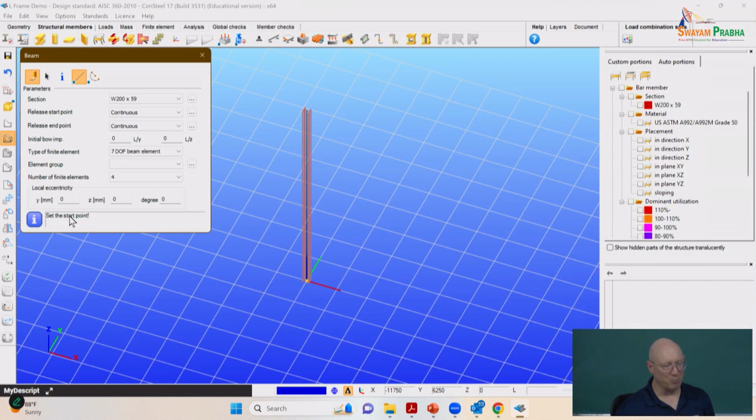So for the beam, it wants us to do a start and an end point, and any point we've already selected, if we wanted to put it into the middle of the beam, it has some control points. The column, you have some control points along the column you can see highlighted there. That's related to the N over here in the lower right, N of 4. Here, I could set that to something else and I would see more points that I could snap to along the column length to insert things.